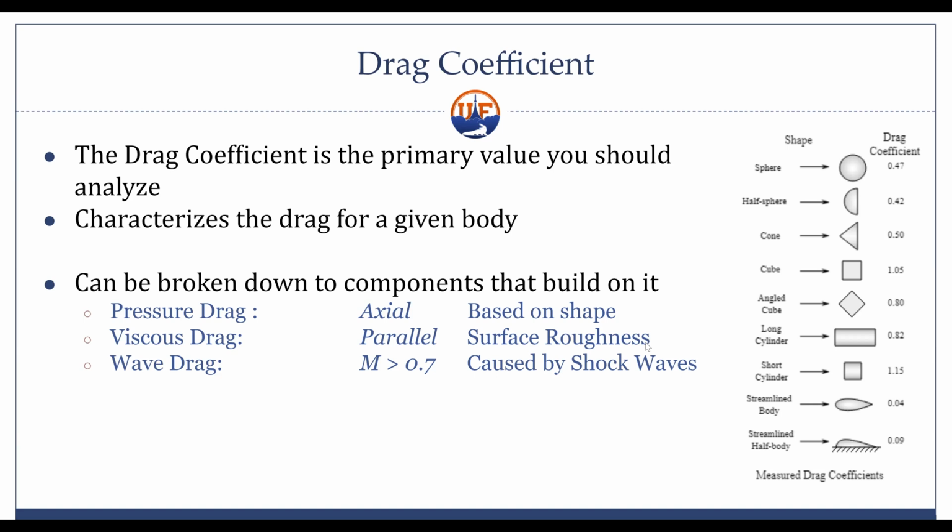So it's really important to choose a design that does not stick in that transonic region. Because if you can go past that transonic region, past Mach 1, then you're just supersonic throughout. Those shockwaves aren't as big of a deal. You still have shockwaves forming on the body, but they won't be as structurally significant. They'll still form, but off protrusions on the body and not just out of a sheer surface. It's mainly that barrier of Mach 1 where you find them.